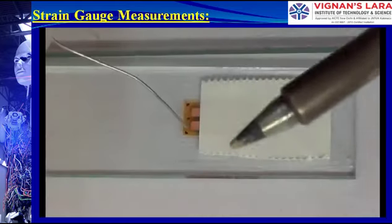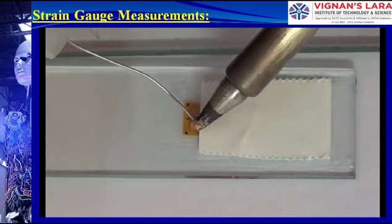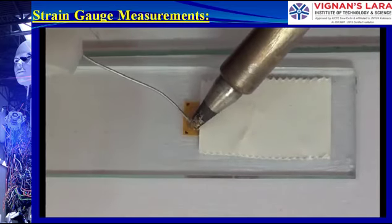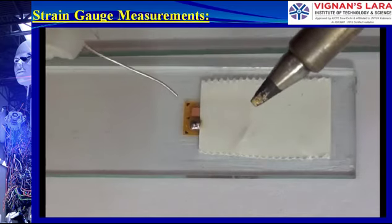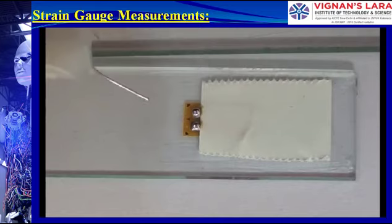The tabs of the strain gauge are also tinned with solder. The end of the solder wire is placed over the gauge tab, then touched with the tip of the soldering pencil, and a small amount of solder is fed into the tab before lifting the pencil away.